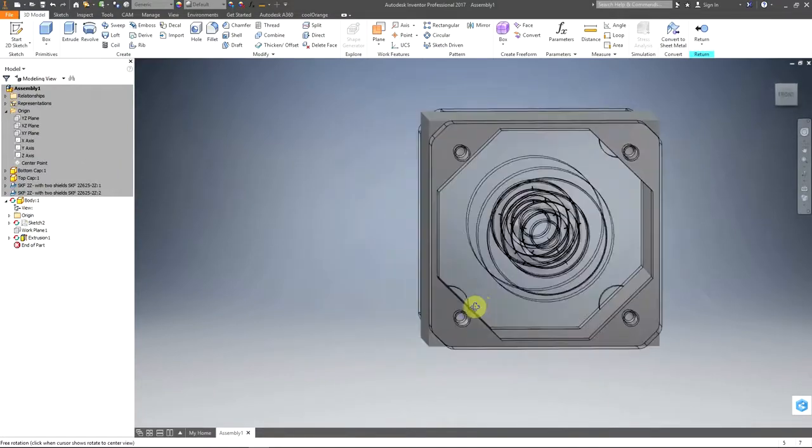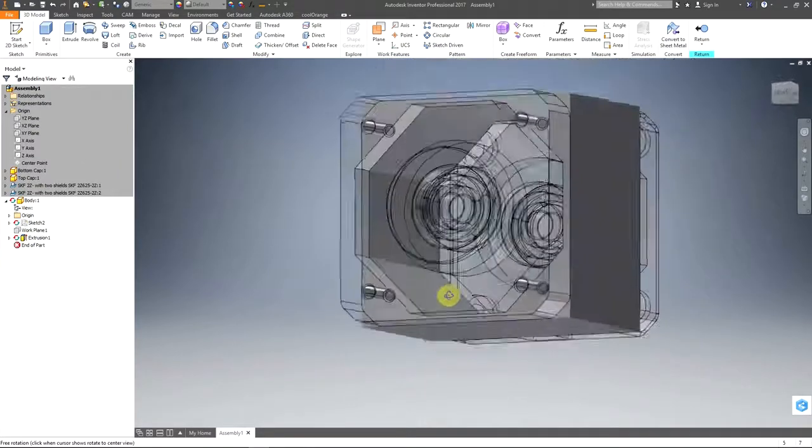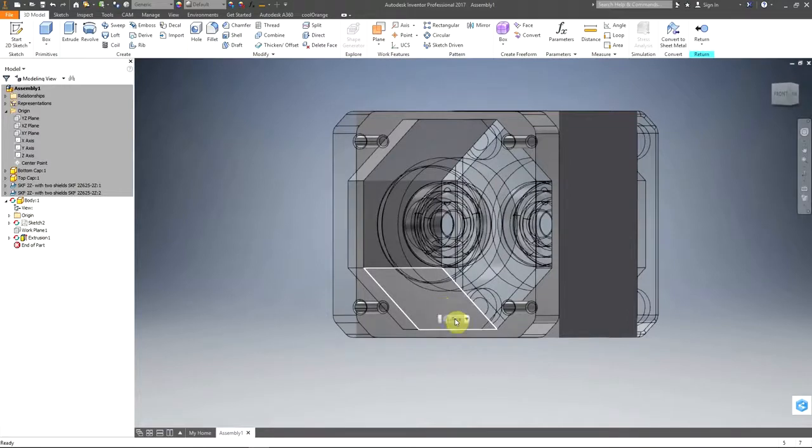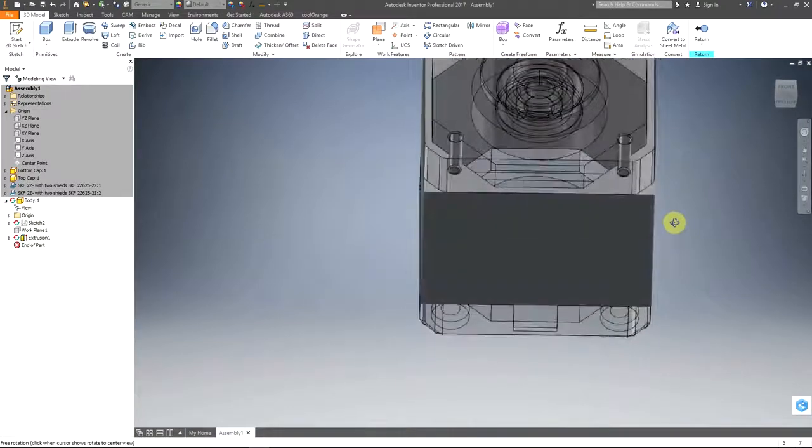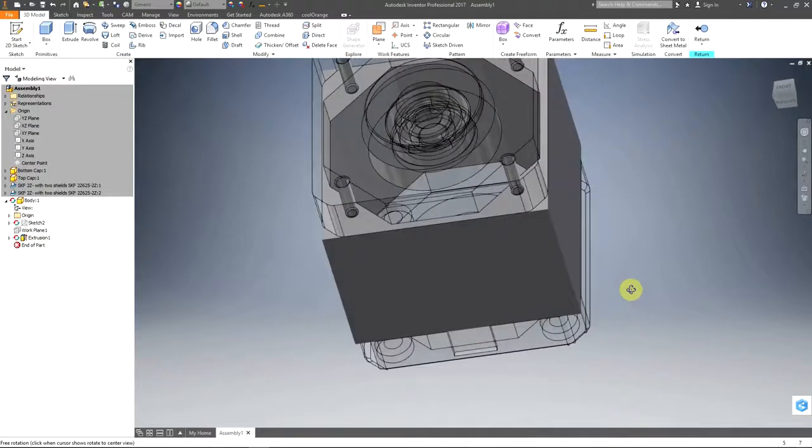So that's popped all that geometry in there for me. So notice we didn't actually have to put any measurements in whatsoever. We were just using all the geometry from the top and the bottom caps, or in this case the bottom cap, which came from the derived part. So what that means is if we ever go and change that very first base part that we made in terms of the hole positions, sizes, the octagon and all that sort of stuff, this body part will also change.